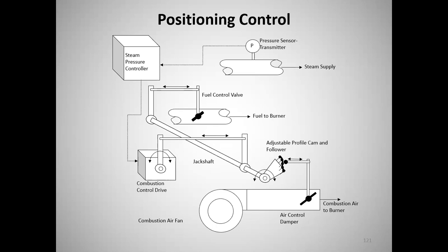Now, if you've got an air preheater, maybe not. But a lot of smaller boilers don't have that. And so they're taking air from the boiler room or sometimes from outside. Well, when it gets colder, guess what? That air is denser. So a cubic foot contains more molecules, okay? If that fan is blowing the same cubic feet per minute, you put cold air in it, you get more molecules of air into your boiler.